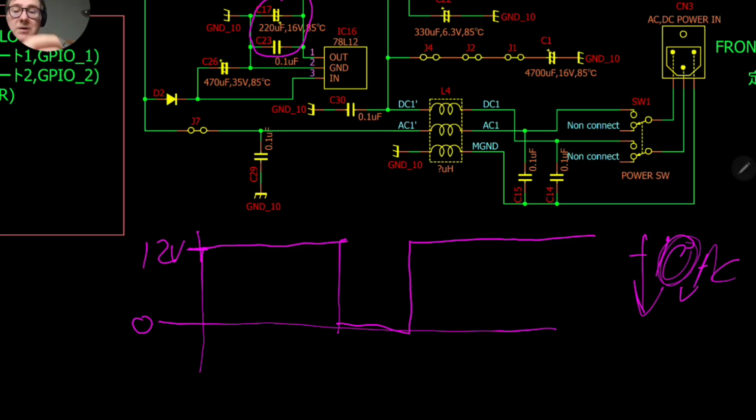We don't want this, so we put this capacitor. It is the same technique, the same idea. So instead of going to 0, here the capacitor charges, and here it will discharge like this. So instead of having an output like this, we'll have an output like this. It will go down a little bit, but will always be close to 12 volts.